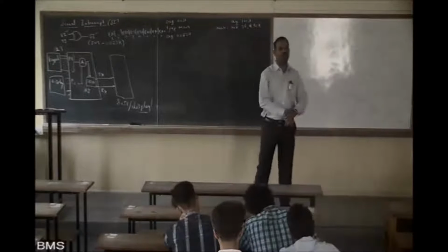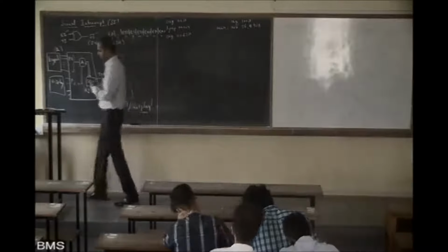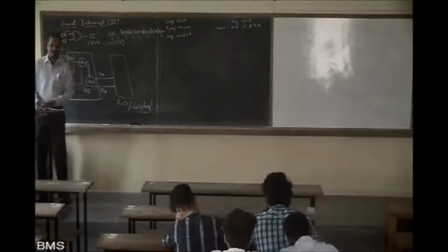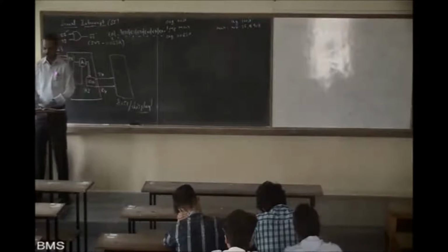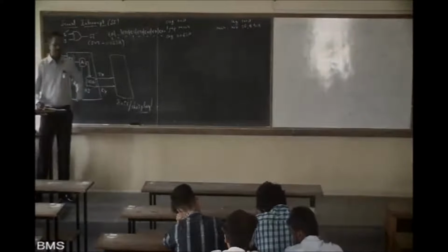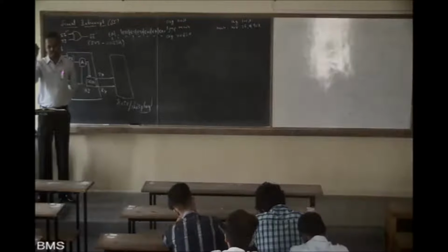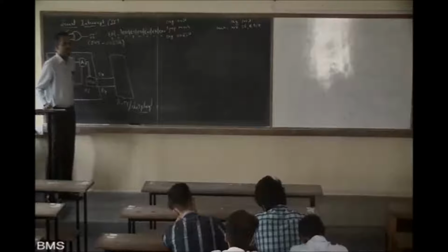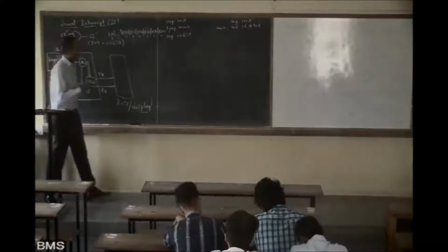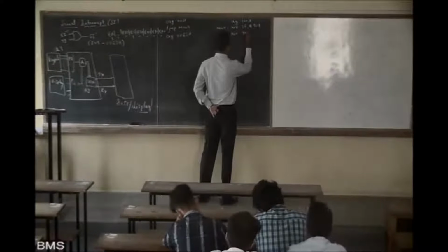Next, what should I do? Quickly. All of you have written a serial communication program. So what is it that you have done in the serial communication program? Baud rate. Where is the baud rate that you are setting? TMOD. Yes, I had to write a value for TMOD. Next I will set MOV TMOD.